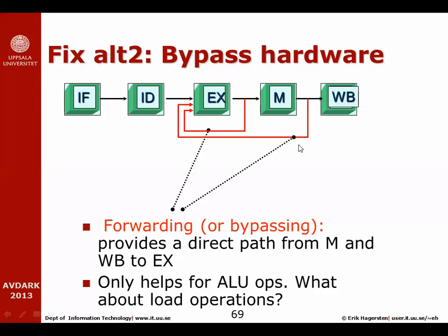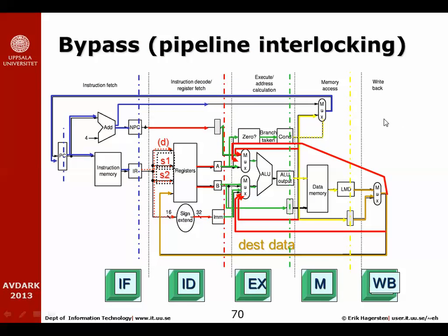So if we create these two bypasses and we make sure that we control which input data the execution ALU uses, either the normal path or one of the two bypassing paths, then we can actually make this whole problem go away. The way this would look in our schematics of this pipeline would be to introduce these red lines here. I have a red line that feeds this mux. You remember this mux sitting here, choosing between the two green arrows. Now the bits controlling this mux, we have to have at least 2 bits of control, so we can choose 1 out of 4 inputs.